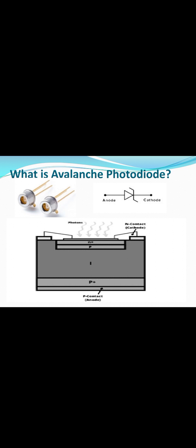These diodes have excellent linearity over optical power levels ranging from a fraction of a nanowatt to several microwatts. If the power received at the receiver is more than 1 microwatt, then the APD is not used, because a PIN diode at this power level provides sufficient responsivity and a sufficient signal to noise ratio. The internal gain of the APD depends on the temperature.